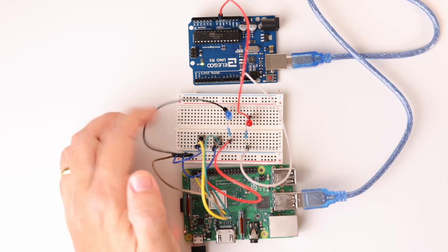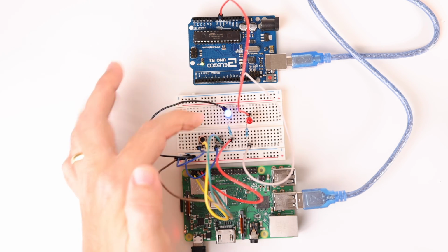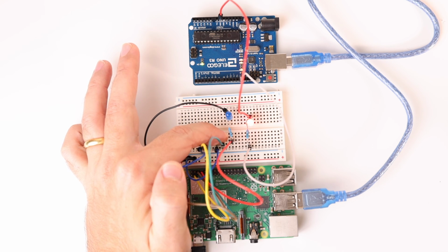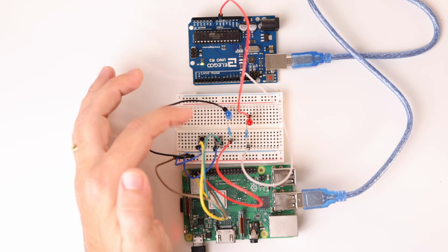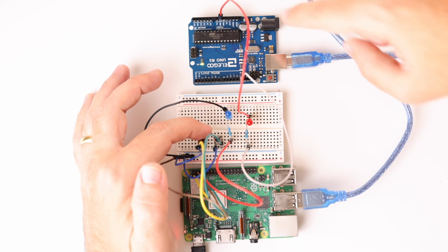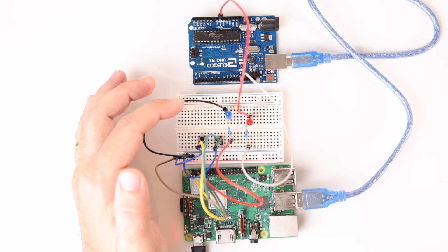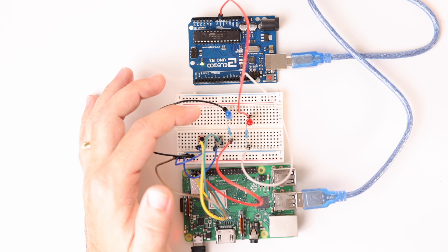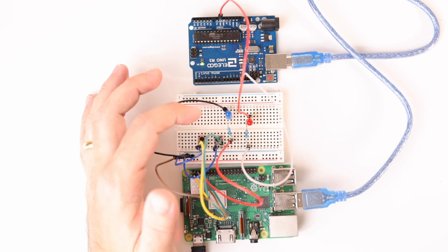And now as we programmed it, if I press PB1, I see that the blue LED blinks, and if I press PB2, the red LED blinks. The interesting part about this circuit is that PB2 is wired up to the Raspberry Pi, but it's controlling an LED connected to the Arduino Uno. For OpenPLC, they're all the same. It's all interconnected, and when you're programming it, it's all part of the same system, so that the Arduino Uno truly works as an I/O expansion to the Raspberry Pi. And not only for pin 13, but you can use actually any pin on the Arduino board for that expansion.